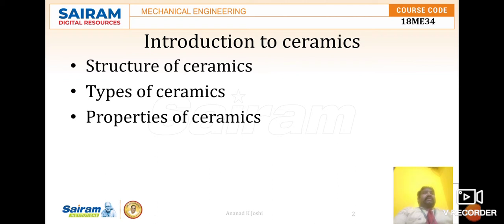The last one is glass and glass ceramics. Glass ceramics form another class of ceramic materials, designed so that crystallization occurs during the processing stage to give a fine-grained polycrystalline material. This is about glass and glass ceramics. Next we will come to the properties of ceramics.